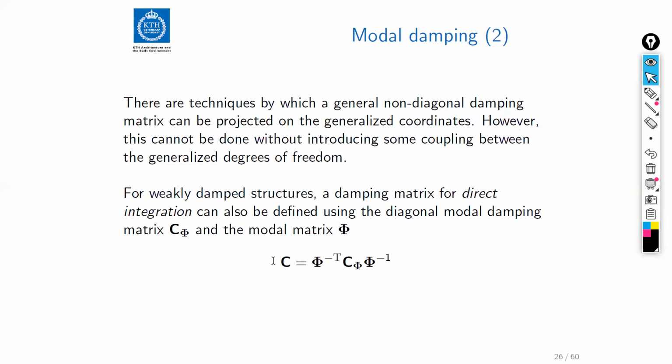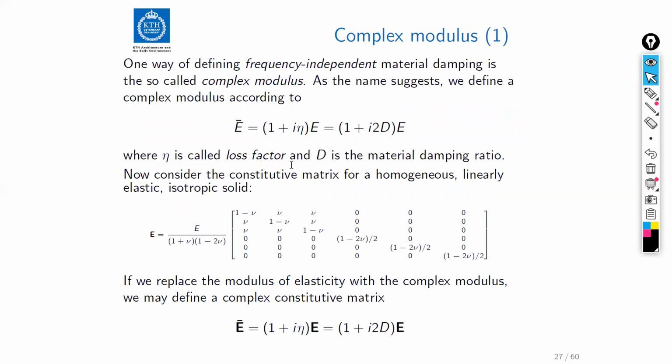But it's an interesting aspect, I think, of how you can start working yourself around these quantities and these equations once you begin to understand them. But one thing that is really important and that you should know about is the concept of complex modulus. Because this is really a way of defining a frequency independent material damping, which is a quite common assumption and also common observation in mechanical systems that are relevant for us structural engineers.